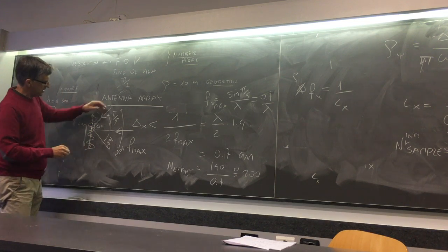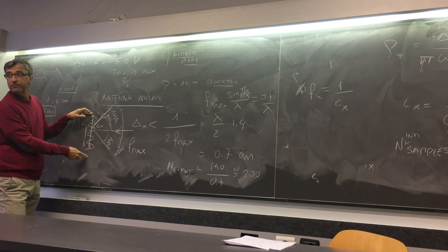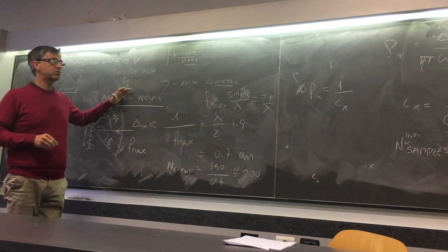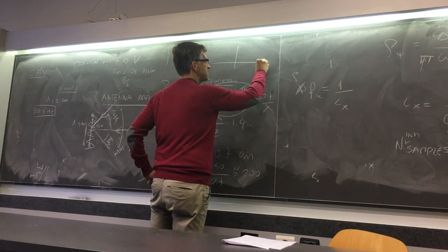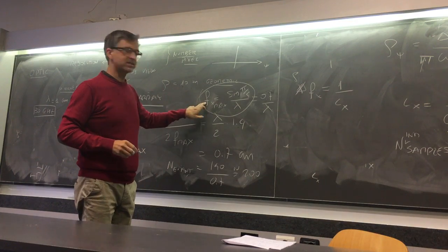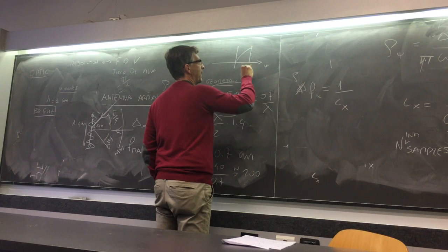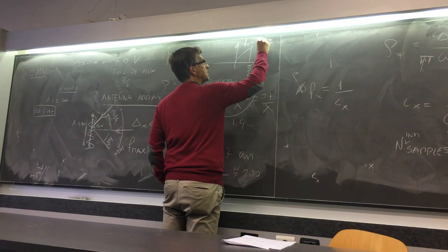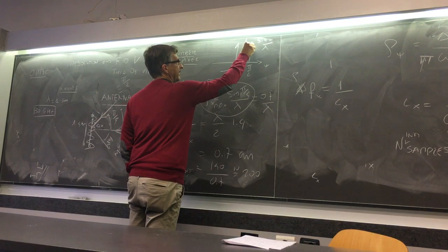this means that the signal coming from this direction provides you a spatial frequency on the array, okay? And the maximum spatial frequency you compute at the maximum angle. You remember this relationship, okay? This relationship means that you make a psi and the frequency is the sine of psi. Of course, up to pi half. Fx is the sine of psi divided by lambda, okay? And in negative, you have the same.